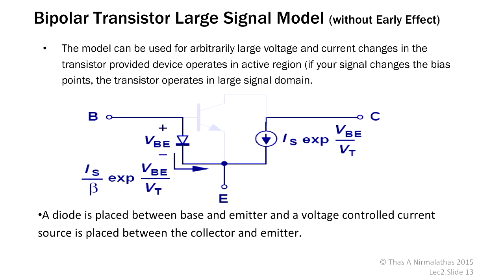VC is the voltage between the collector and the emitter, which you set to 1 volt DC. But when you connect a very large input voltage, the DC bias points will fluctuate. If that is the case, you are operating your transistor in a large signal mode.